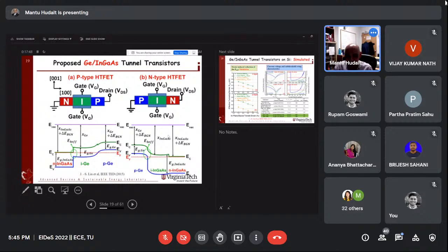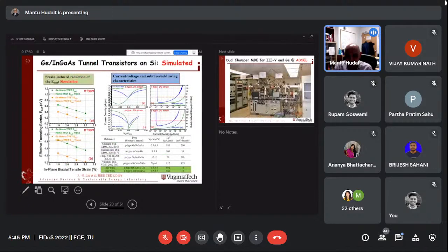So in the lab, this student simulated the data, and it looks like this, you see here, this work, the green color, sub-threshold slope at 10 millivolt per decade, and this work was funded by Intel. Intel is very happy, take it. So Intel asked me, are you able to make it a 40 millivolt per decade sub-threshold slope? I told him, forget it. Give me millions of dollars, maybe I can try that, because you need lots of materials growth to figure out the interface. And we're going to show you some of the data there.